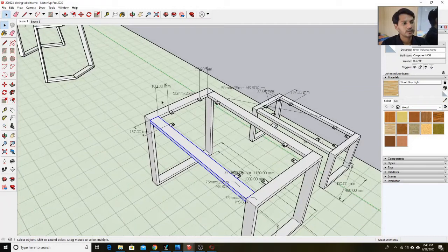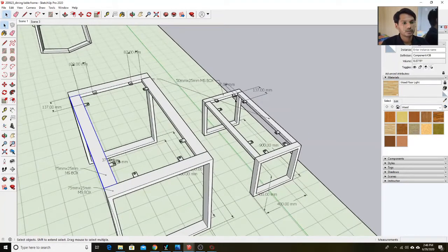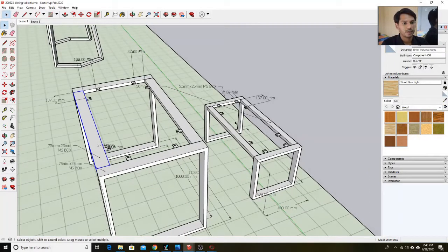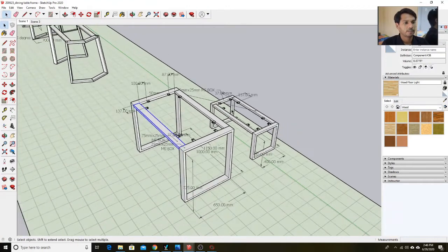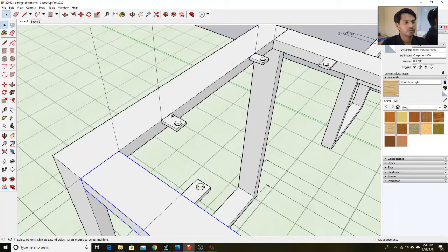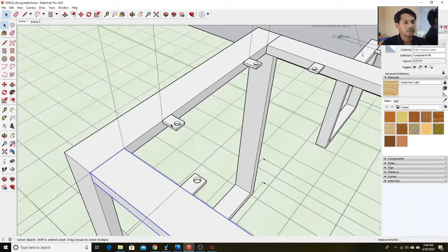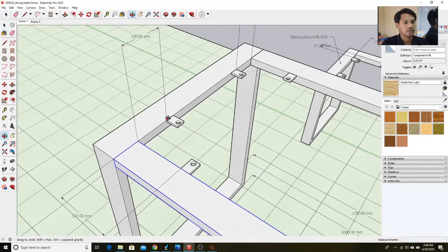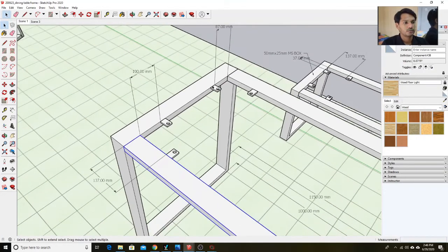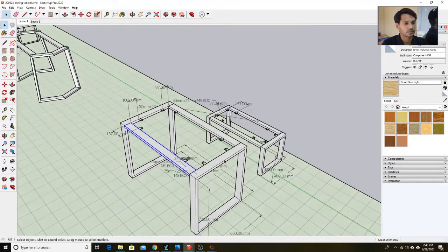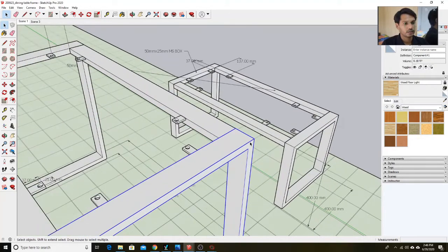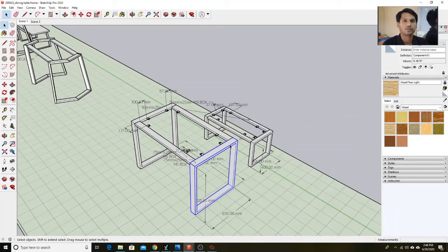So these sections are 75 mm by 25 mm in width by length ratio, and the smaller one, on this bench which we are making, is 50 by 25 mm, about 1.5 inches lengthwise and 1 inch widthwise, which are directly gas welded on the surface line of the top support. As you can see, this is completely welded in a diagonal manner. That specification will come into a working drawing.